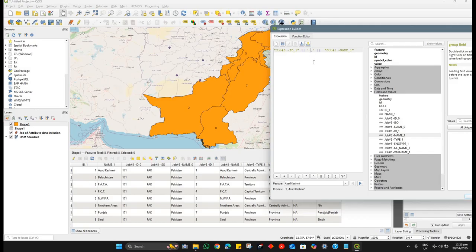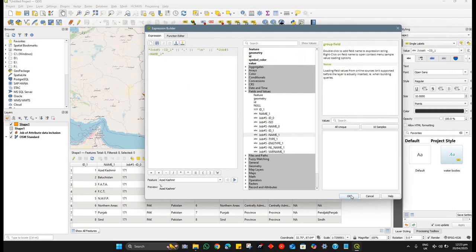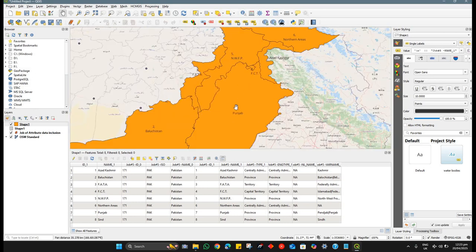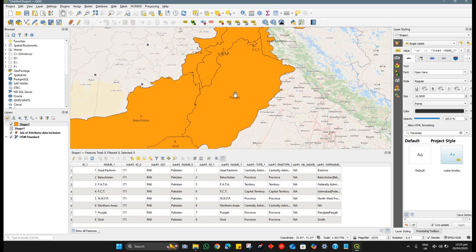And if you want to add a comma, and again you want to add the name of the corresponding provinces below this number, you can use the over number here, this one, and concatenate symbol. So in this way, you can add multiple labels to a single shapefile, a polygon or the point or the line. So click on the OK, and here we can see that to each polygon vector shapefile, the corresponding number ID and the corresponding name of that province appear.